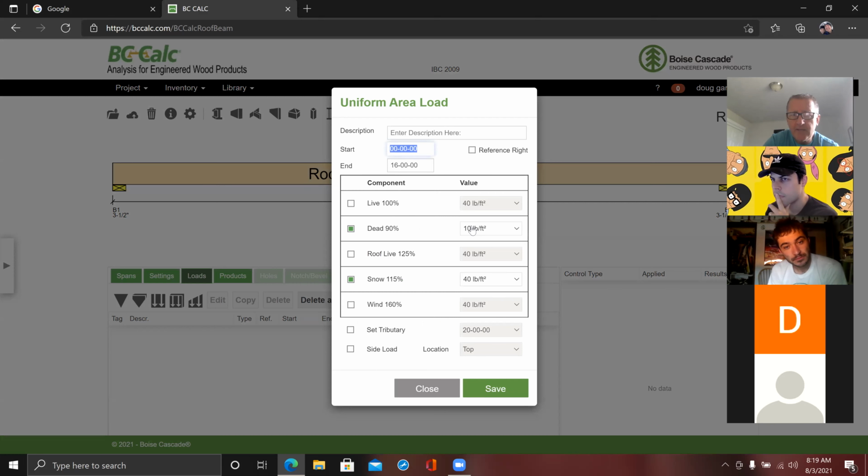And for a dead load, we have 15 pounds. And for a live load, we have 25 pounds. And that's what we just used. And notice I didn't even have to calculate 800. This will do it for me. Does that make sense? That's how I got 800 a minute ago. As I said, a total of 40 pounds, 15 plus 25, and then times 20.